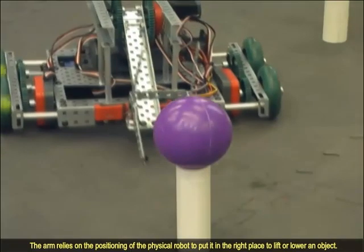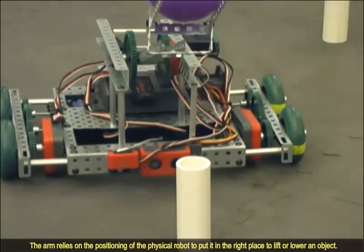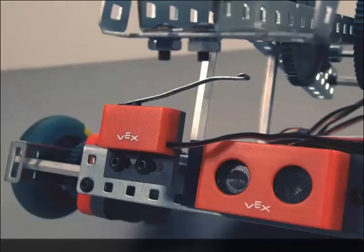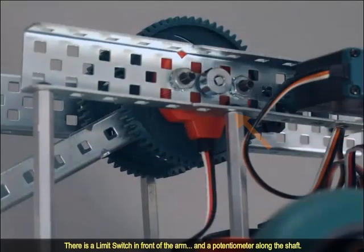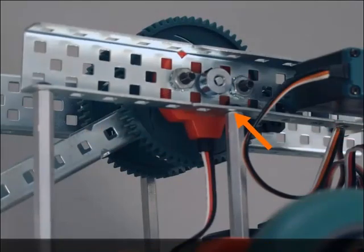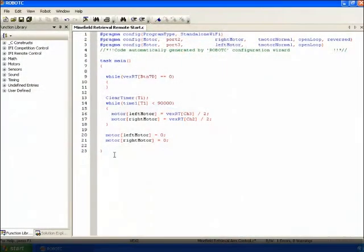The arm relies on the positioning of the physical robot to put it in the right place to lift or lower an object. There is a limit switch in the front of the arm and a potentiometer along the shaft. You will learn how to program these sensors in the sensing section. Now that we've covered the basics, let's get to work in Robot C.